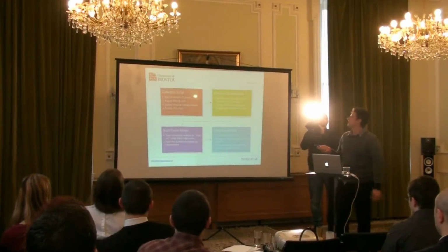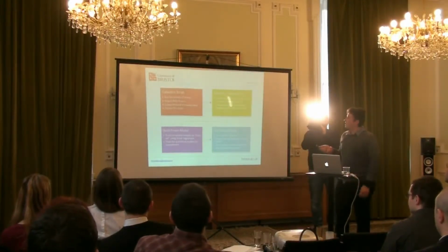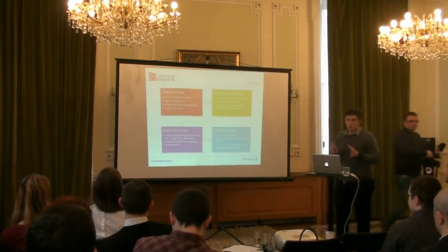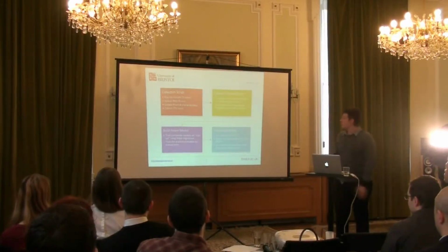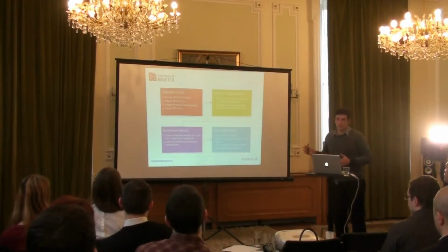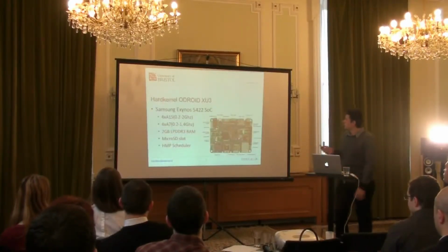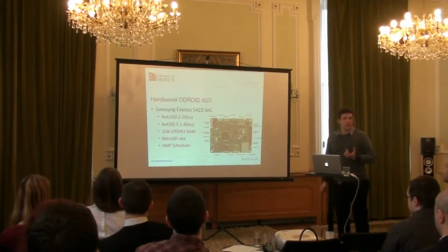At the moment this is my current methodology. I'm running a collection script which runs my workloads and collects all the events. Then I'm analyzing them, finding the best small set of events that predict the power most closely. Then I'm building a power model based on those events, and finally I'm testing the power model on a test set that is completely different from the one that I used to train the model on. What's integral to my research is having the ability to actually run the workload and monitor power at the same time, so I can train the model.